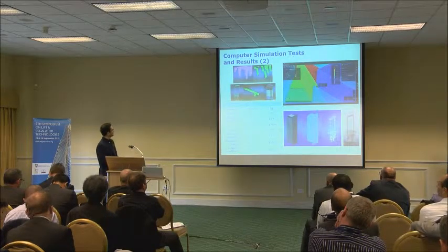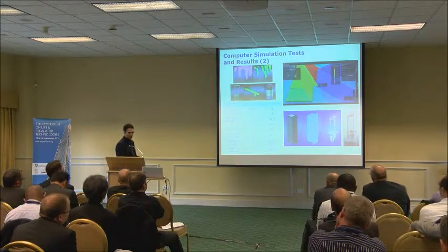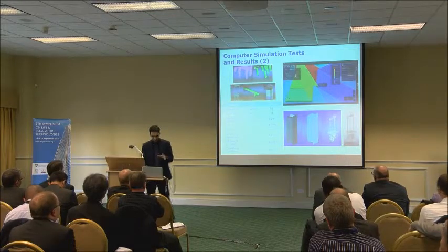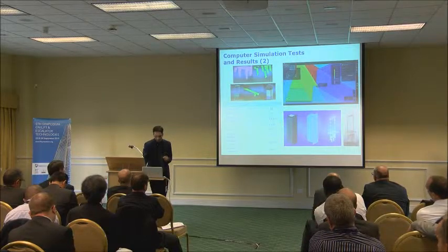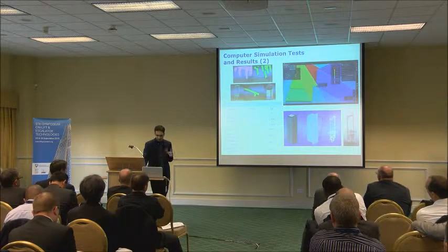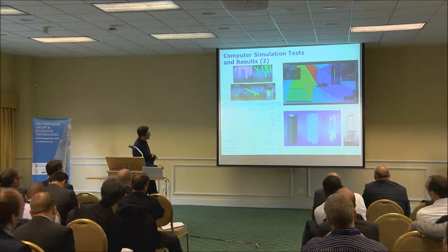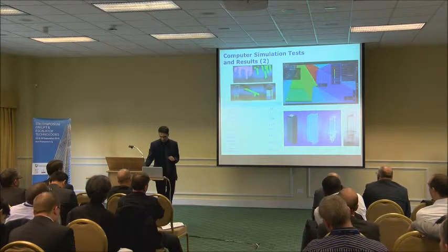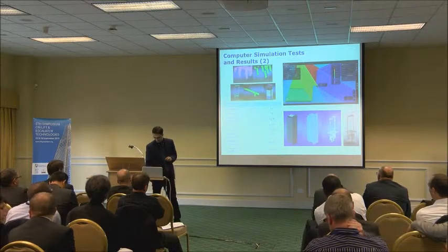Some of the basic parameters we used for this case study were based on a car mass of 1,000 kilograms, a frame mass of about 400 kilograms, a mass per unit length of 0.6 kilograms per meter, and an effective area of 69 millimeters squared. The stiffness of the cable is 7.82 kilonewtons per meter. The springs for the different positions, since all of these are connected by spring and damper, have a stiffness of 29 kilonewtons per meter, and the damping coefficient is 20 kilonewton seconds per meter.